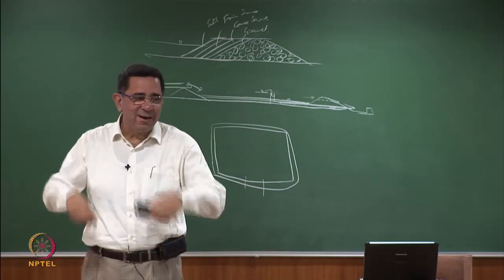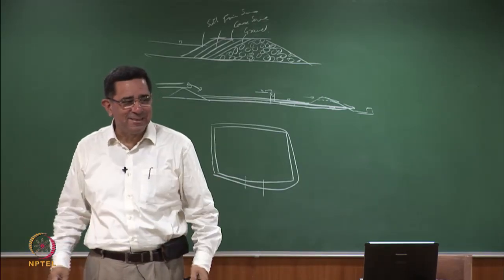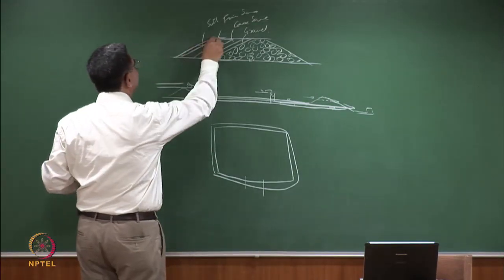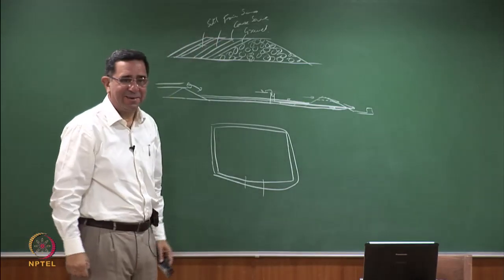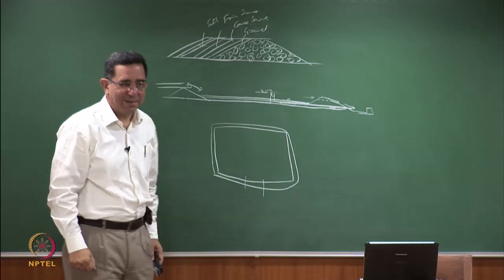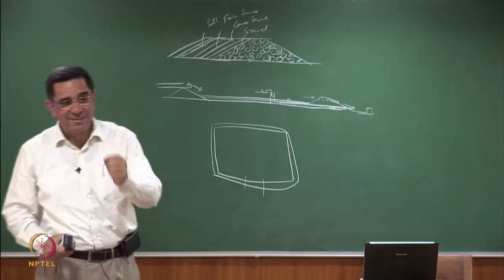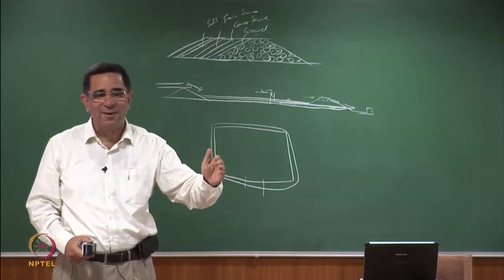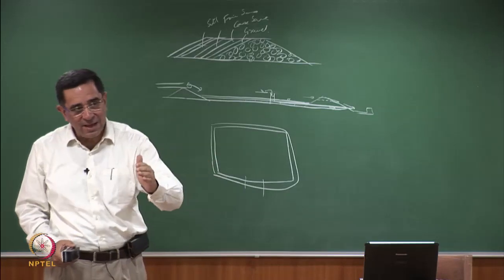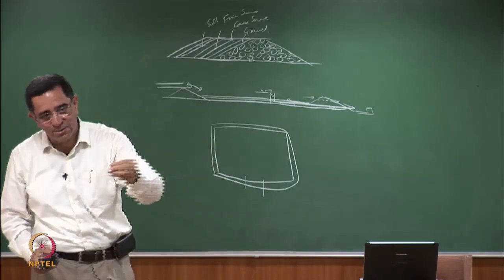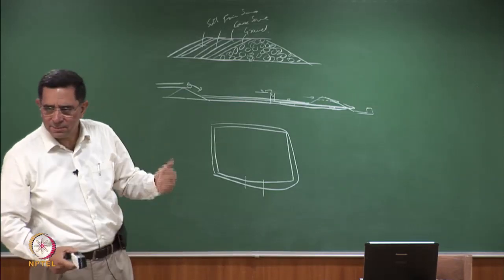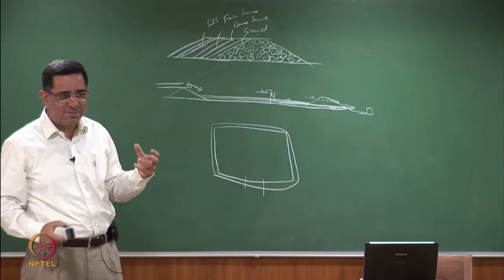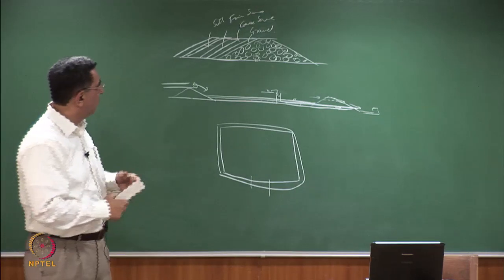So you come to a designer like Manoj Datta and he will say, okay, let's stop this dusting from taking place. Let's make yet another filter. Sand, gravel. How do you like it? Any problems? This is the correct way of having an upstream slope which does not erode and still has a silt barrier inside which will not allow the fine particles to go through it. Does it look sensible or no? It's very expensive now. The expenses are going up. Anybody would like to punch a hole through this?